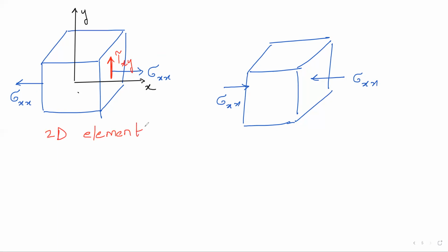Please. Okay. What will be the direction of arrow on the left-hand side? Downwards, right? Are you getting my point? So tau, again, XY. Why is it again XY? Why didn't I write a negative XY? Because it's on the negative face. In the negative Y, you still write XY, okay? Okay, what about the direction of arrow here? So there will be a stress YY, right? Agreed? Okay, what will be the direction of arrow here? Upward, right? Okay.